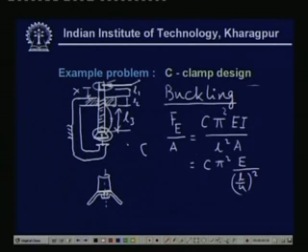C is a constant, and that depends upon the boundary conditions. Depending upon the boundary conditions, the failure may start at different regions. Now, here one reasonable guess of boundary condition will be, let us assume that this part is clamped, that is, here we are considering a buckling of a beam which is fixed at one end and free at the other end and subjected to a pressure P. Then of course, the value of C will be in that case 0.25, and then we have the Euler critical load for buckling.